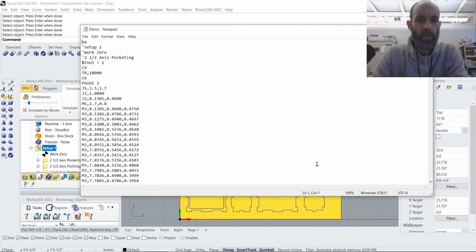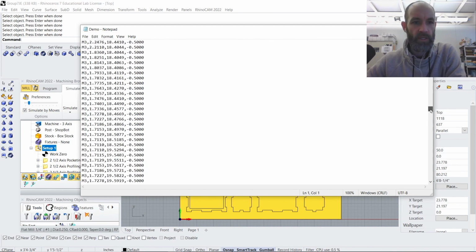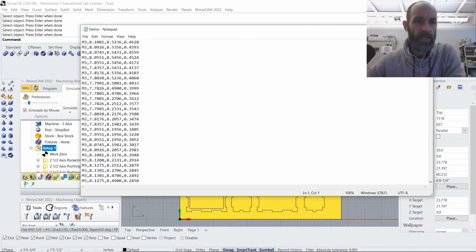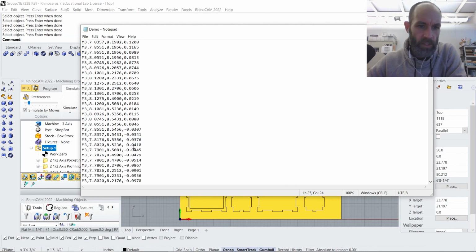It will pop up a window on the screen, and it will show you the actual G code that will be used to drive the machine. What you see here are each one of the target points, as it's going to an XY coordinate and a specified depth. Here with a decimal value like that, I'm guessing that it's an approach motion to a specified point.